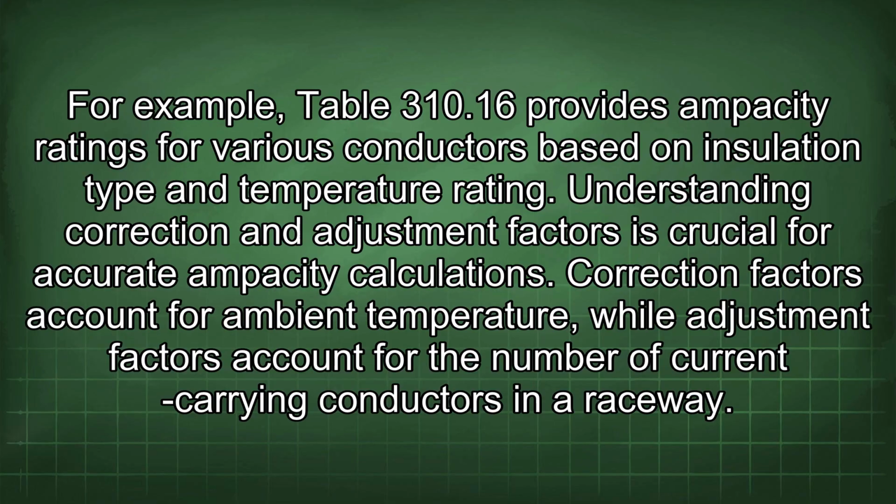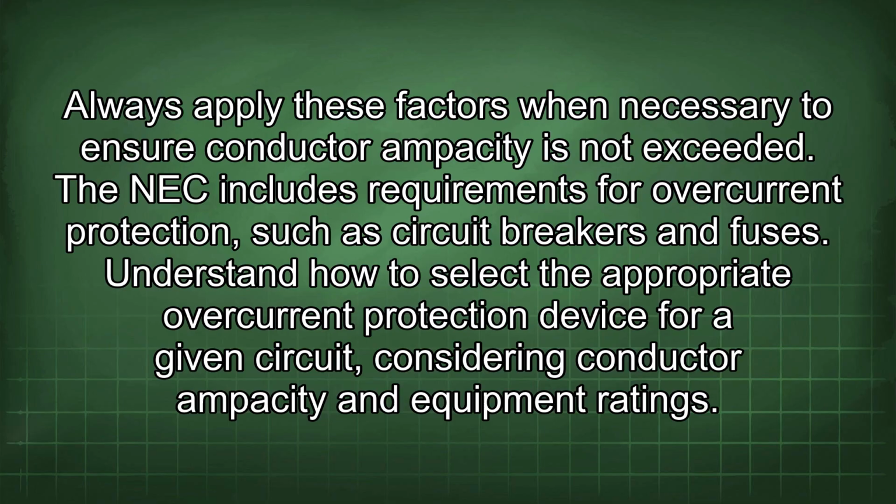Understanding correction and adjustment factors is crucial for accurate ampacity calculations. Correction factors account for ambient temperature, while adjustment factors account for the number of current carrying conductors in a raceway. Always apply these factors when necessary to ensure conductor ampacity is not exceeded.